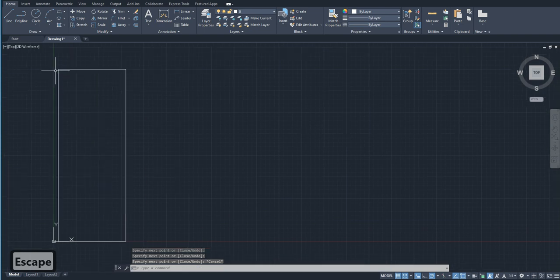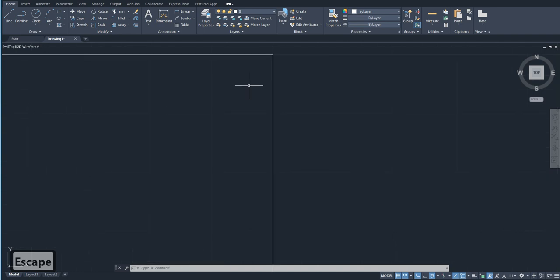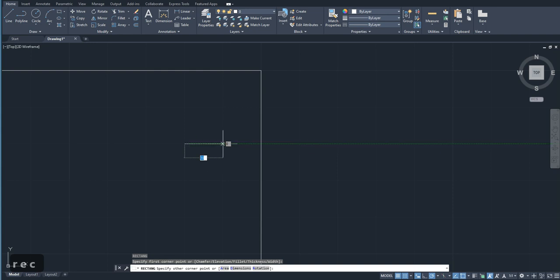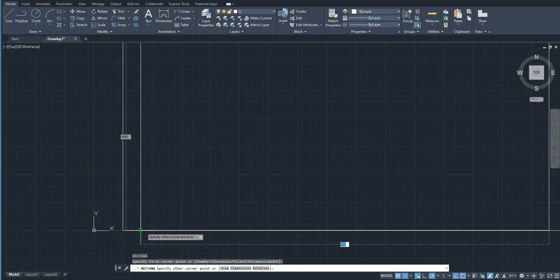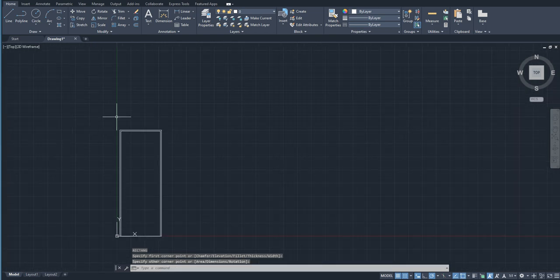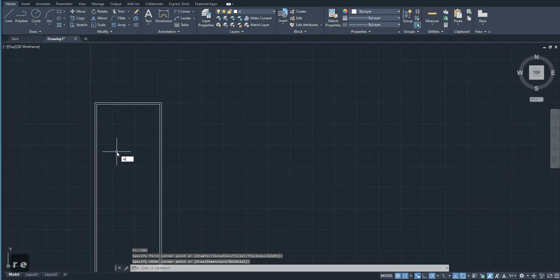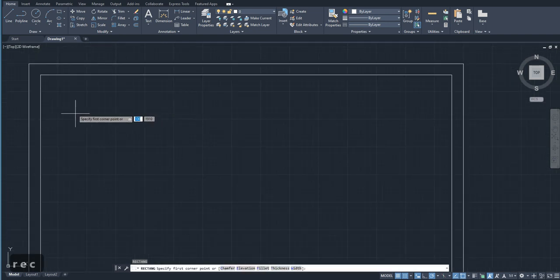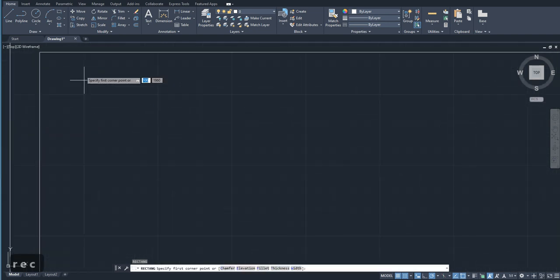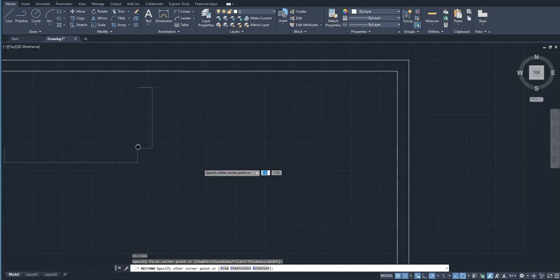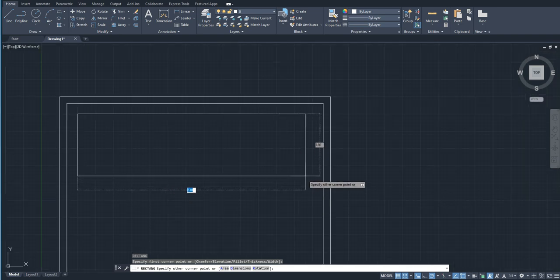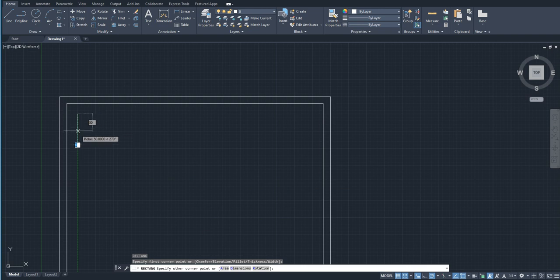Now I'm going to create a small rectangle inside of our box, giving the space 10 mm for the jamb. Here we have it. Now I want to make a window. Now since I know that this one singular spacing is 10, I will know that this particular spacing would be 30. So 30 mm from the side, and this particular spacing is 50.